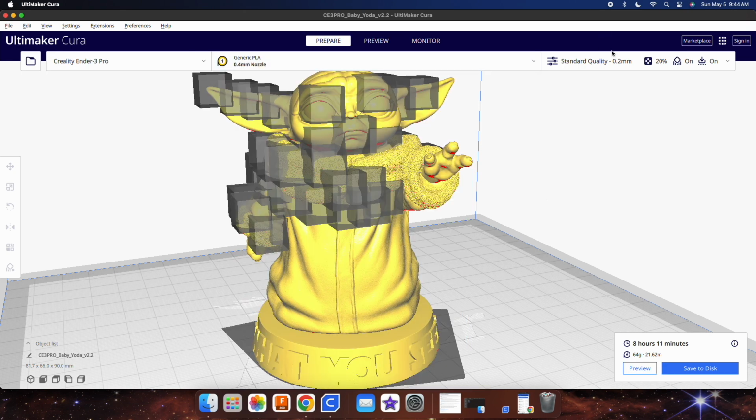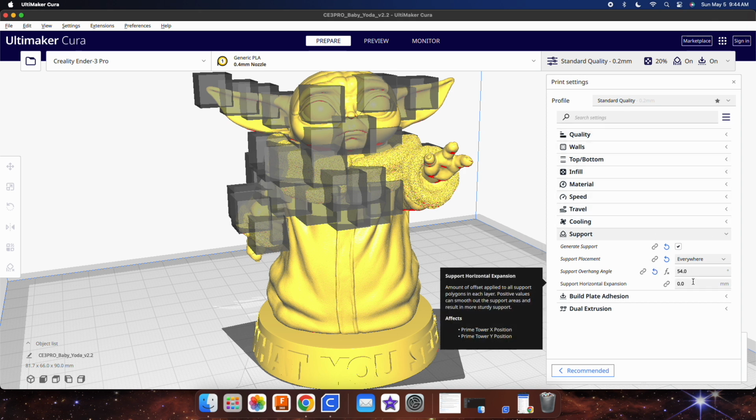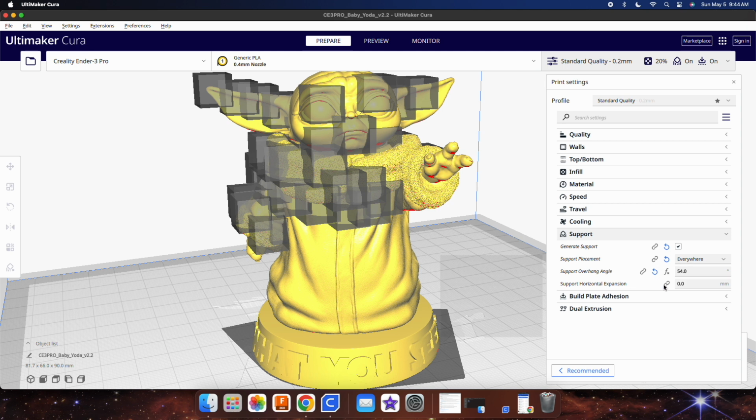So now that we know how to do that, we can also change certain aspects about the support. Just like we can change the density of regular 3D prints, we can also change that in the supports. So what we're going to do is, Cura had an update recently where they don't show you all of the settings, I guess to make it easier to use. But if we go to customize here, actually, if we go up here, right now it just has custom selection.